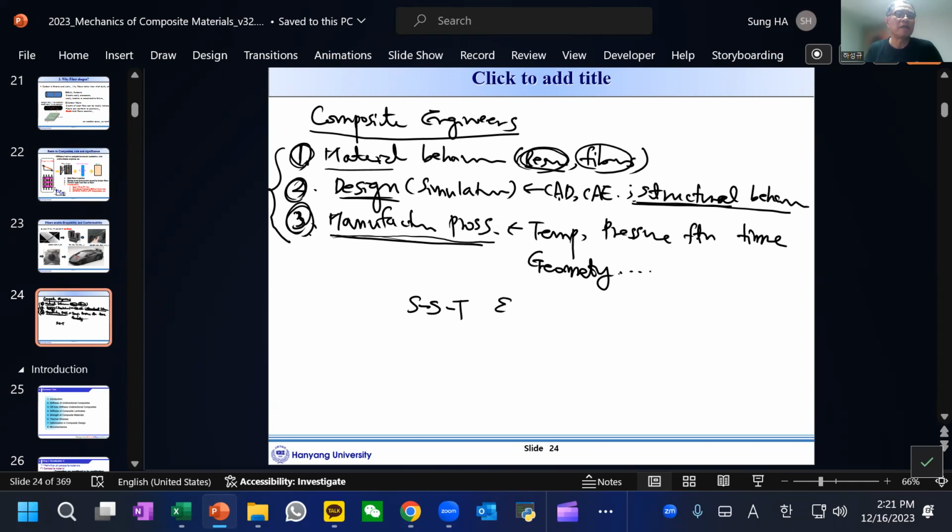So simply you can say strain, and the compliance and the sigma, plus the CTE. You need to understand this concept, the stress and strain and the temperature relations. We always have to have it. Now this composite makes this one more generic and anisotropic. Now this is the stress-strain relations and temperature relations. And now the next one is the equilibrium.